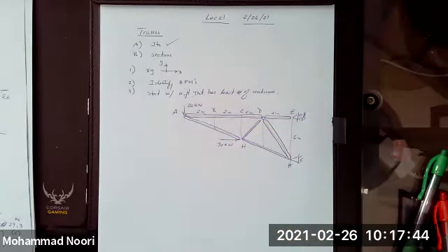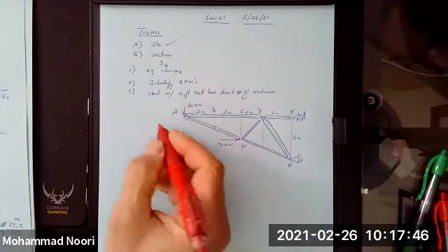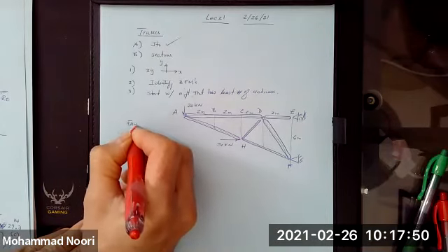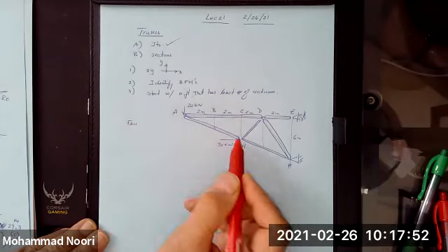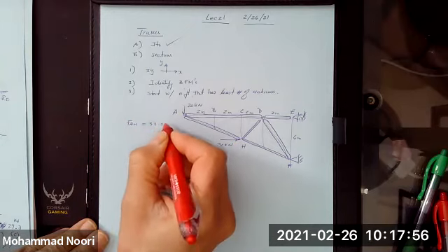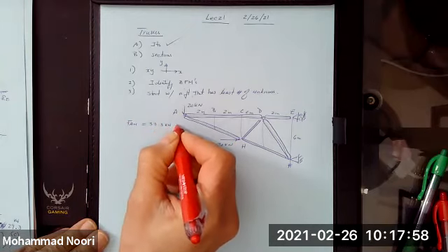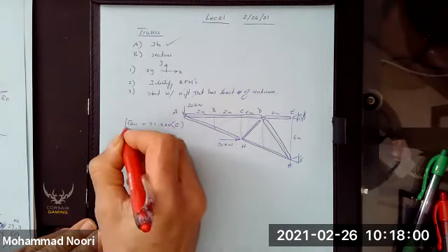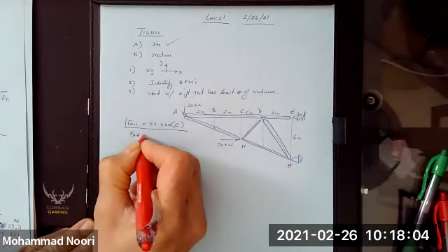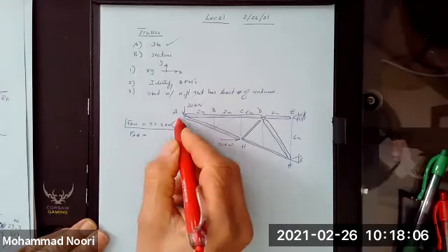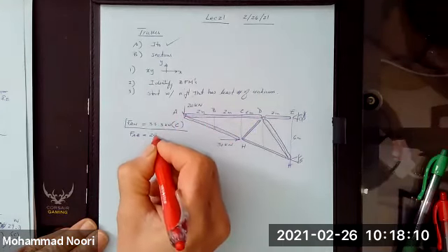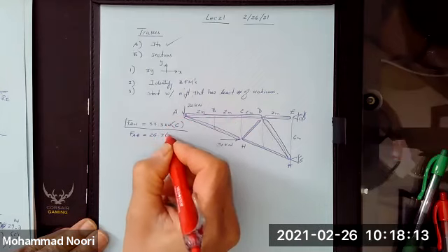All right, so we solve for most of the unknowns. F of AH, which is this one, came out to be 33.3 kilonewton compression. Force in AB, which is this member, was 26.7 tension.